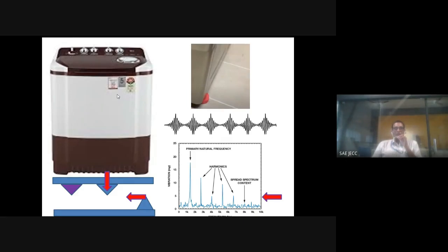That is one type. And one more thing you can see in this enlarged part, that is a vibration isolator. If you want to isolate vibration from the surroundings, you can use these isolators. So these two, isolation or redistribution of mass, that is attenuating the vibration.